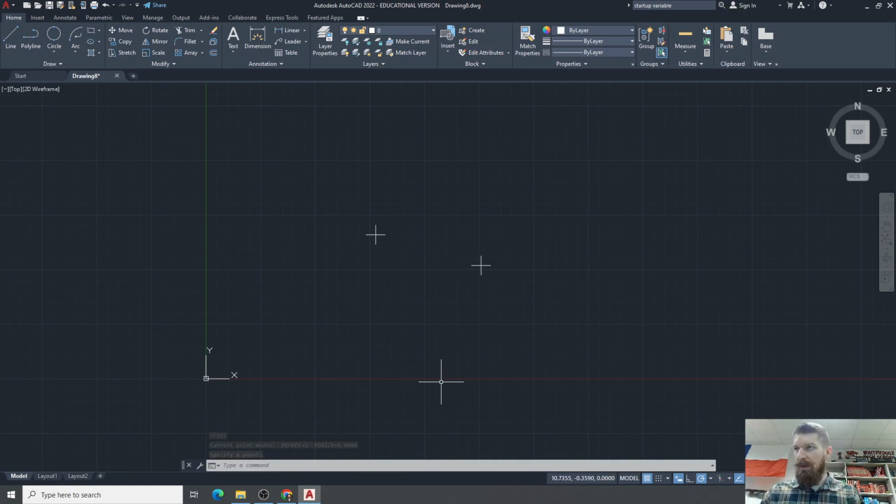Okay, let's do polyline, and then we'll be done. What is a polyline? A polyline has special features that make this object more versatile than a line. Three features are most noticeable when first using polylines. It can have a specified width, like a boldness. Several segments can be connected, and they're one object, whereas if you use the line tool, they're separate objects. And number 3, a polyline can connect arc segments. You can have arcs within your line. It can also have a tapered width.